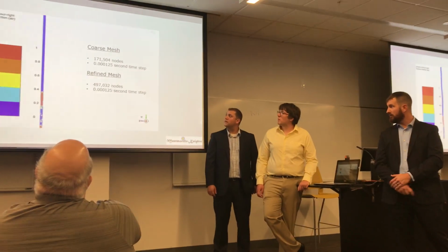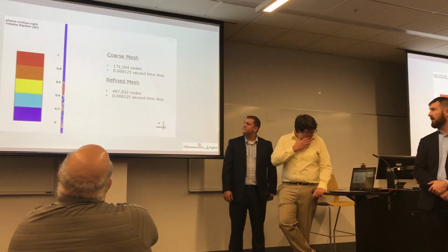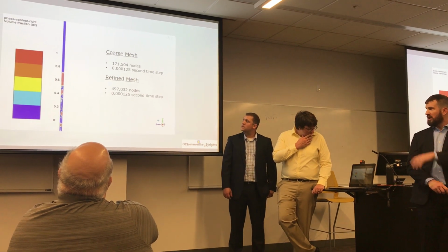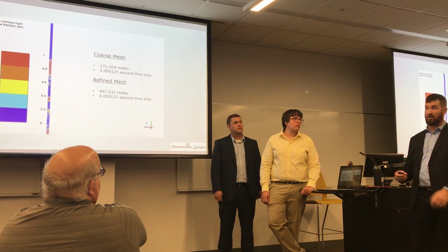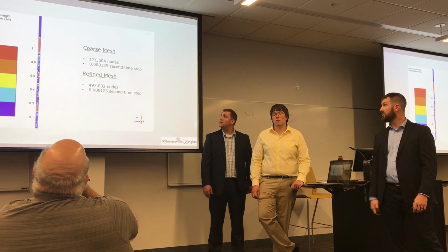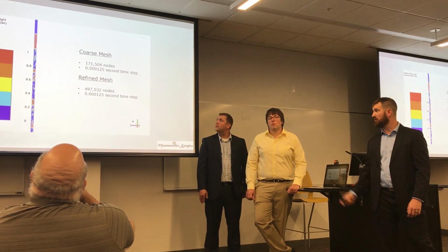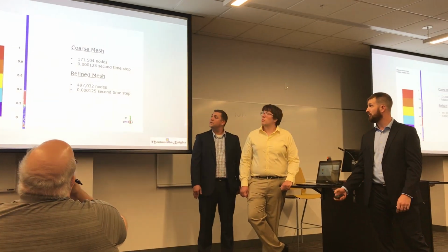Moving on to pilot, here's another phase contour animation. This one's about halfway up that big riser. Want to point out that these animations are 2D partitions we made so we could see inside the pipe, but all the simulations were run in 3D. And you can see again, this one has a lot more stable results, but this one was turbulent, so we ran it with a K-epsilon model.